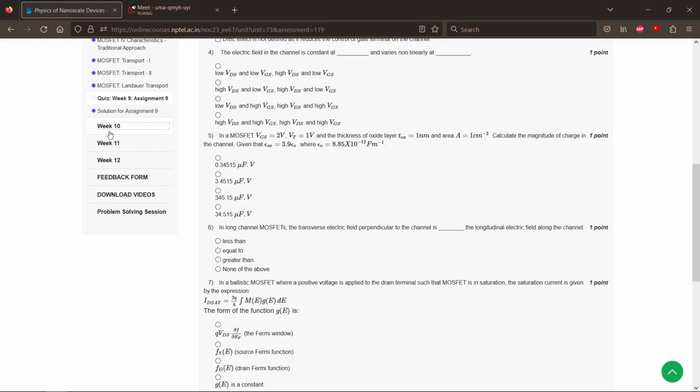Right now we do not consider that, because when we say ballistic, we assume the electron to be a classical particle traveling without any collisions or scattering. The wave picture will essentially come when we are looking at devices below the 10 nanometer or 7 nanometer limit. Below that, even the ballistic model will break down. So the pure quantum mechanical treatment that you are talking about occurs at around the 5 to 7 nanometer limit.